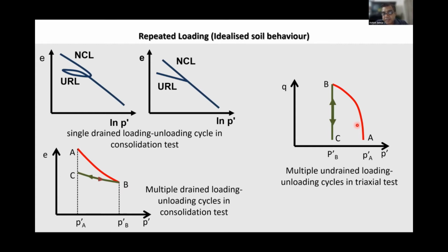If you look at the stress space, starting from A, going up to B, and if I unload D to B and then reload, like any kind of dynamic load I apply, it just goes up and down with no change in any additional strains occurring, and no new shear or volumetric strains being developed.